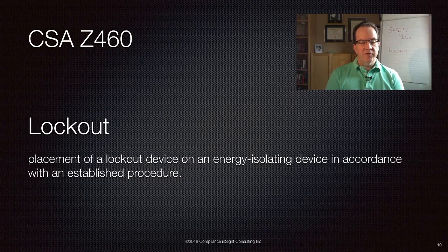So Z460 defines lockout as the placement of a lockout device on an energy isolating device in accordance with an established procedure. So you need a lockout device, you need an energy isolating device, and you need an established procedure, right?